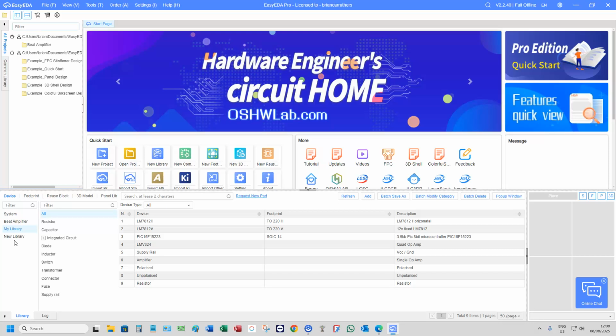And if you wish to transfer your schematic to a PCB, then it's prudent to use the footprint you plan to use on your PCB. As a demonstration, we'll make 3 components with the same symbol but with different footprints, and hopefully this will become clear. Let's start with a resistor, 1/8 watt vertical mount, horizontal mount, and SMD.